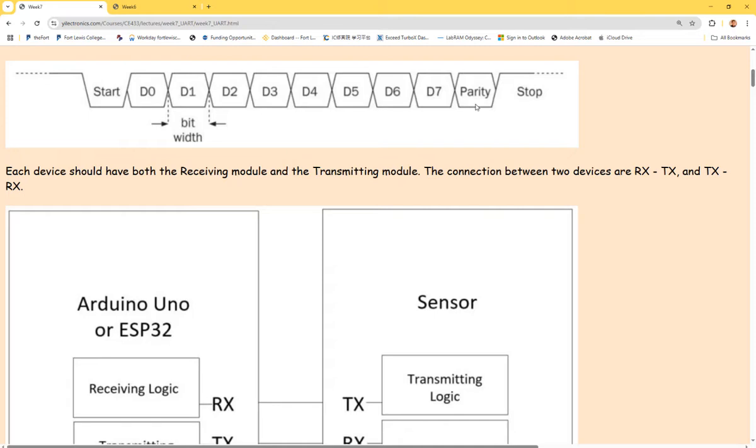bit by bit. And whenever all the bits are sent, you should stop it. So it's getting stopped by the transmitter. Okay, the transmitter does it. Keep in mind, not the receiver. The transmitter pulls it up to 1. Okay, this could be a really common interview question, right? What is the starting bit and ending bit of the UART communication? So starting with a 0 and ending with a 1. So the transmitter puts it up to 1 to stop it.